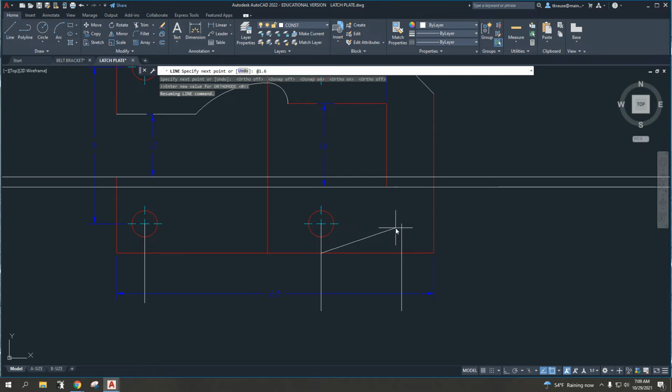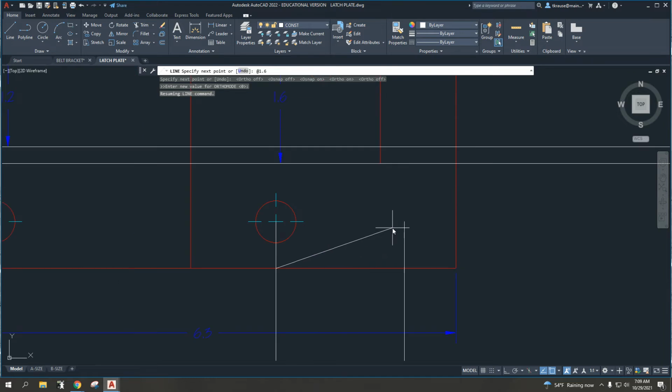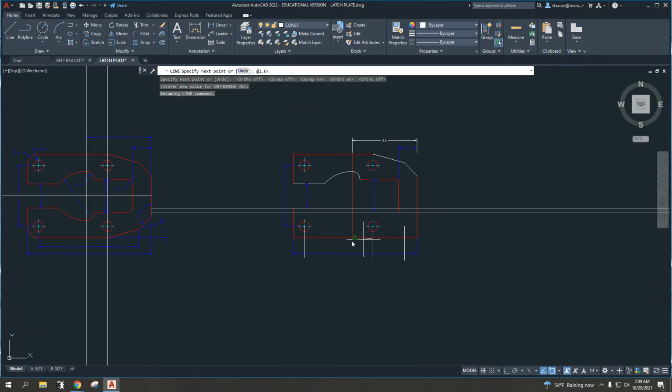Okay, and that angle, which I'm going to put in next, so Shift, comma. Again, pay attention to see what's up on my command prompt. It's the @ symbol, 1.6, open alligator, or Shift, comma. Okay, angle, and now the angle that I need to give the computer.